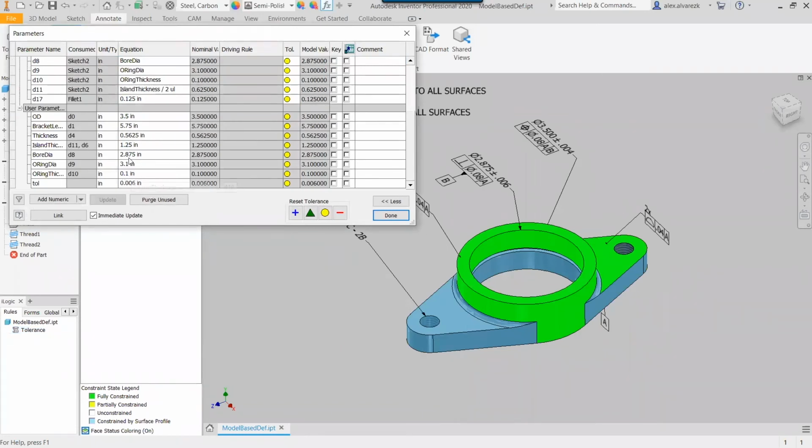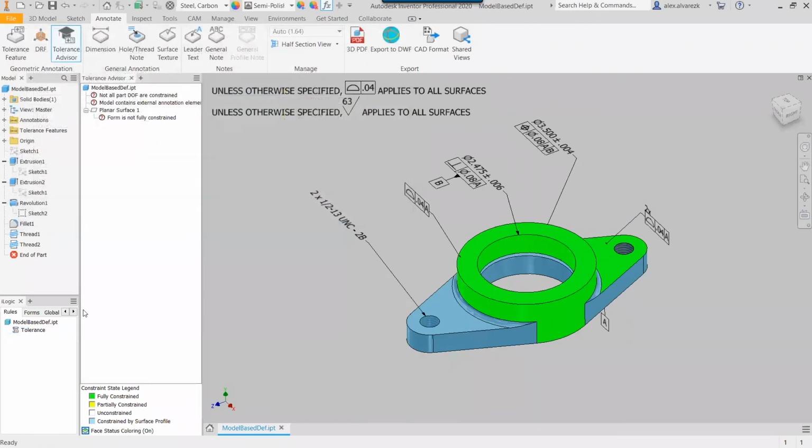I'm going to go ahead and drop this down, right? So the bore diameter drops down to 2.475. And again, I typically run rules with one single rule that calls it out, but we can have that run automatically. But anyways, 2.475, and my tolerance dropped down to 3 thousandths there, right? That was a question that I got a while back, and that is possible if you wish to do that. It takes a little bit of a workaround, but you can have different tolerances for different size features here.